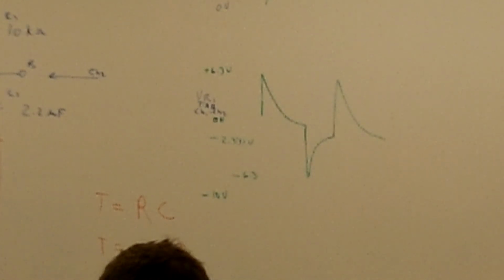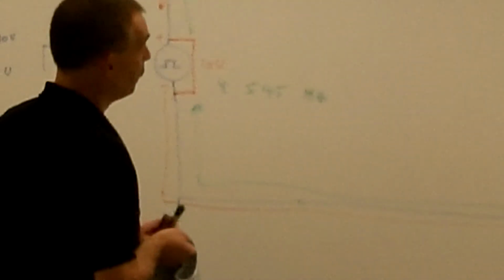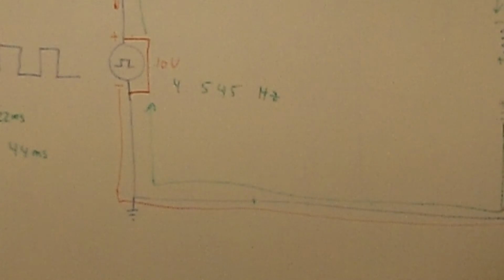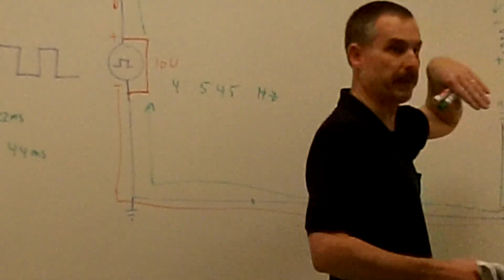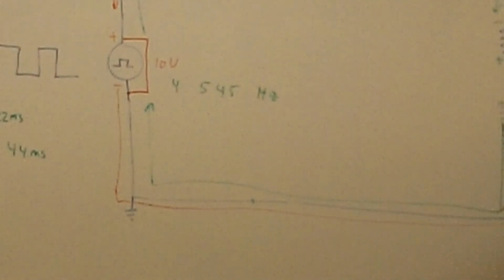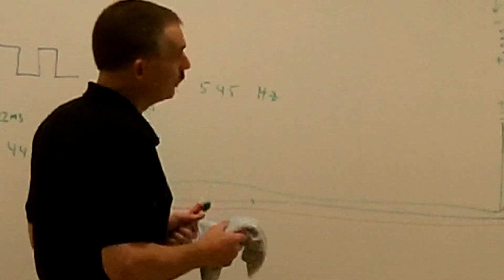You'll see these are some pretty definite characteristics of certain signals that you'll see when you're using your oscilloscope. When you see that shark fin, you know that there's some capacitance in that circuit. If you're measuring a signal and you see a signal like this, you know that it's an RC circuit. You know that there's a capacitor and resistor in there and that we're getting that discharge.